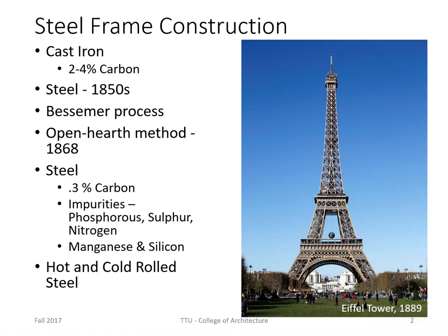Basically, steel is cast iron which has had its carbon reduced to 0.3%, and the impurities you find in cast iron, such as phosphorus, sulfur, and nitrogen, have been taken out, which makes it stronger and less brittle. Then to make steel, we add manganese and silicon, and those two things give the steel more strength and flexibility.